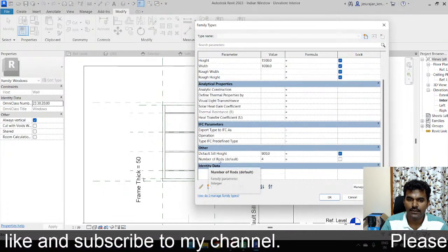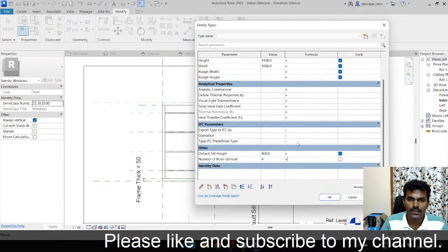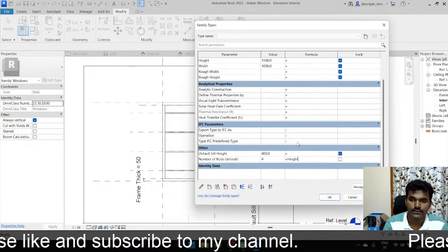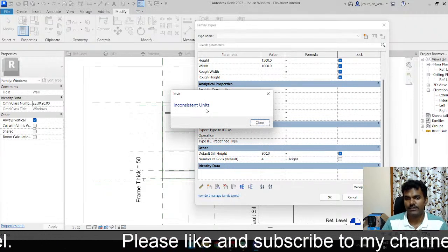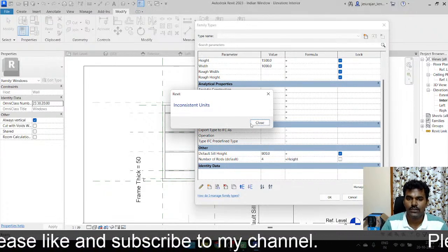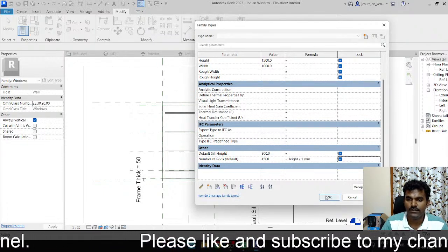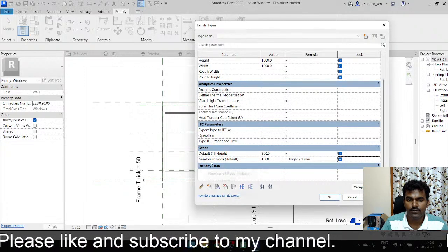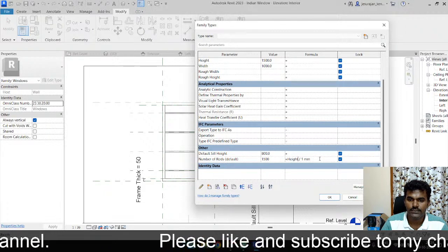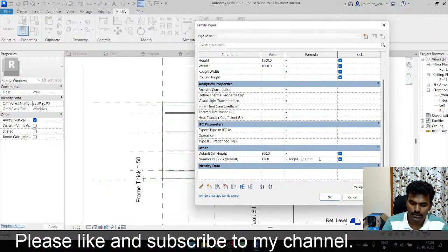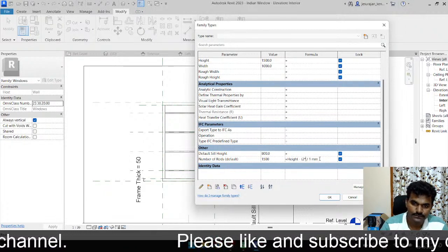You see here, number of rod, here I'm going to say equals Height, enter. Inconsistent unit. I know Revit is going to say inconsistent unit. Just close, divided by 1, enter, and Revit will accept. What do we get here? Number of rod equal to 1500. But here what we need? Height minus bracket 2 multiplied by frame thick.